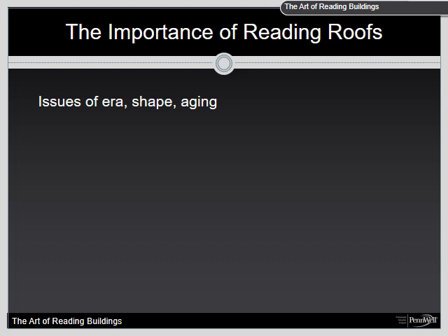well as the aging. And of course, with the aging, it's important to note that a lot of times on East Coast style roofs, those roofs have multiple layers of asphalt shingles, which increase the dead load tremendously. Often at the fascia board, you can see anywhere between 2 or 3 layers of shingles on the roof.